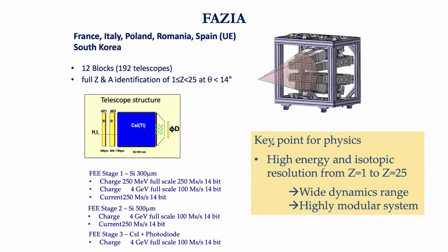In the case of this detector, the signal is digitized. So you can measure the details of the shape of the signal, not only the amplitude: the rise time, the fall time, and many other things that you can correlate. Today there is this machine learning approach. It's not the same, but it's like an image recognition system where each shape corresponds to a specific particle.